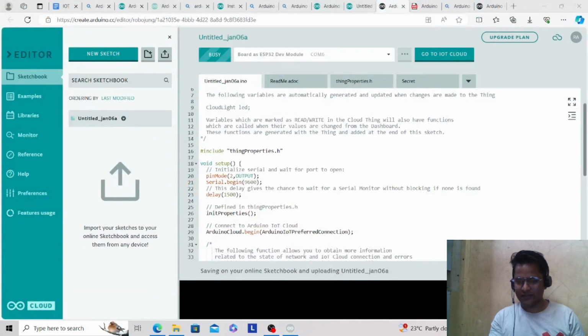So on the background it will be actually running. Without the Arduino Client Agent, you will not be able to see the Arduino ports here, and also you will not be able to upload the program using Cloud IDE. So it's kind of an important thing.